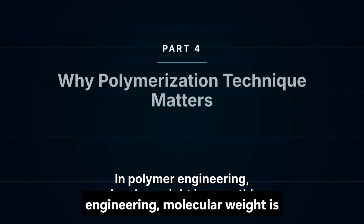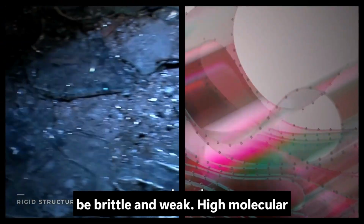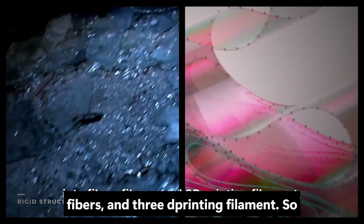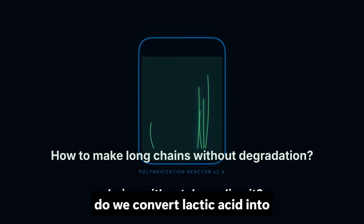In polymer engineering, molecular weight is everything. Low molecular weight PLA may be brittle and weak. High molecular weight PLA can be processed into films, fibers, and 3D printing filament. So the central engineering question is, how do we convert lactic acid into long chains without degrading it?